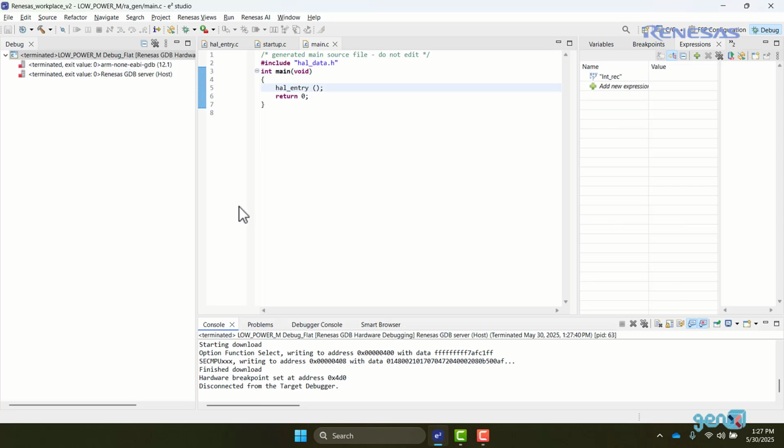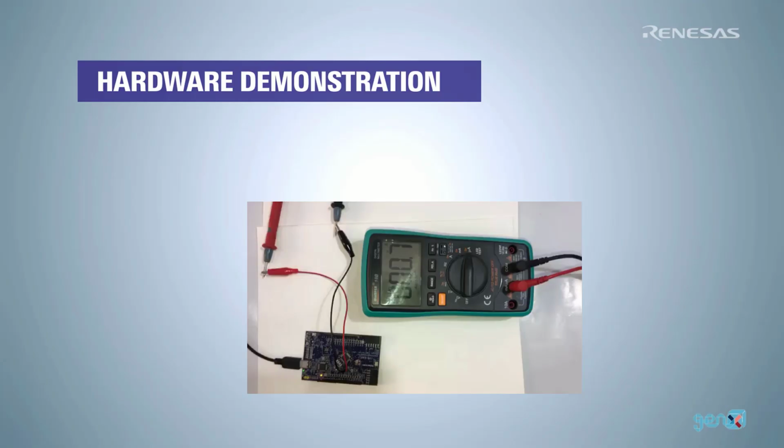Now program is uploaded on board. Click on terminate button to stop debug session. As debug session is active, processor will consume more power. After terminate button is pressed, disconnect USB-C cable, then connect it again.